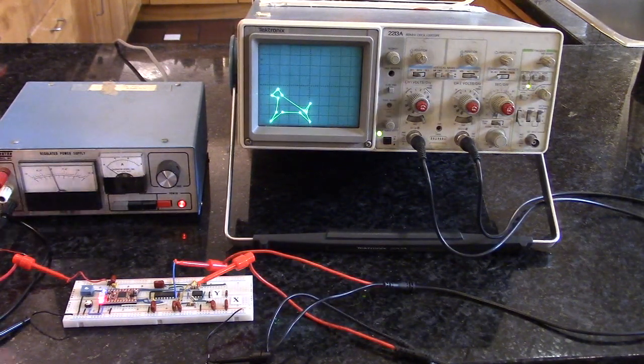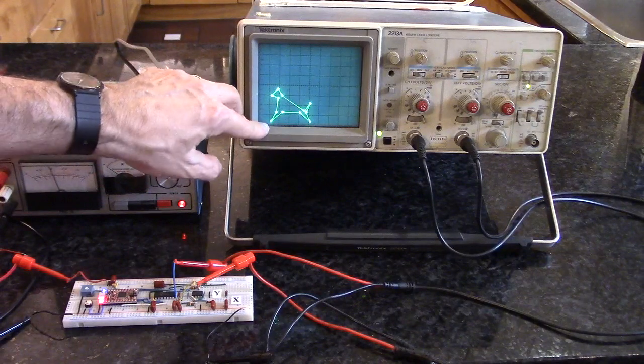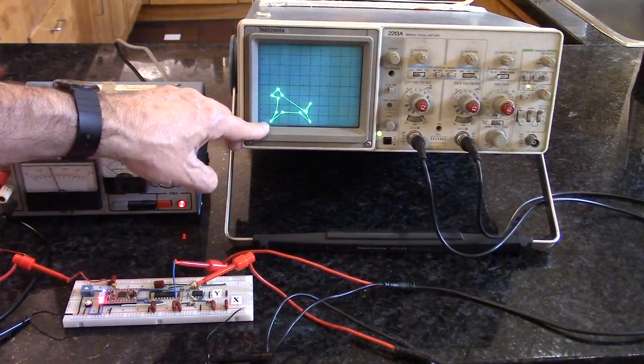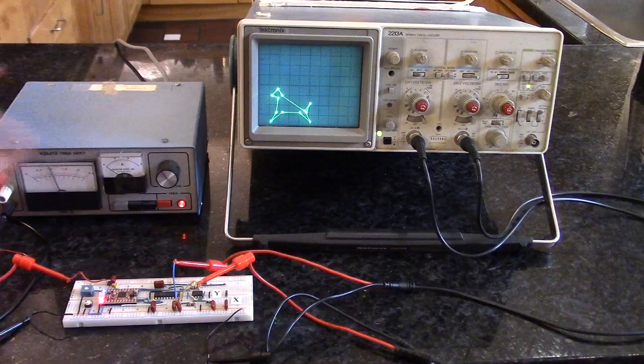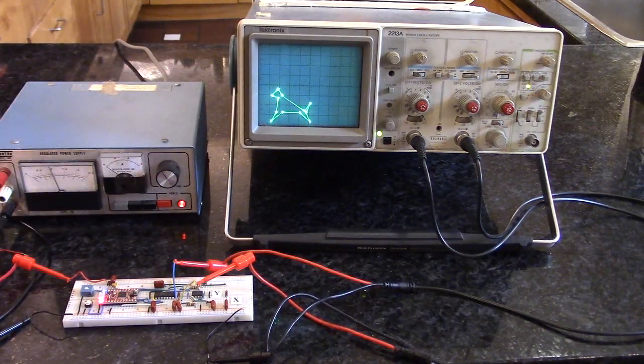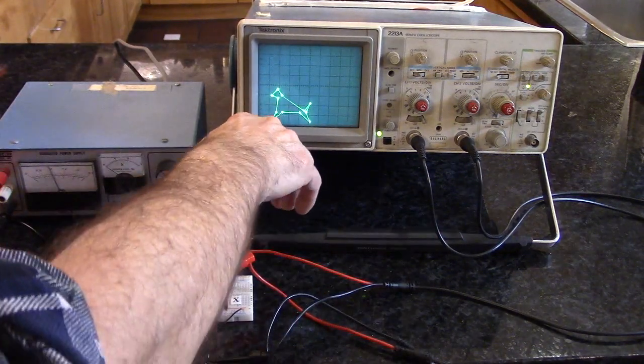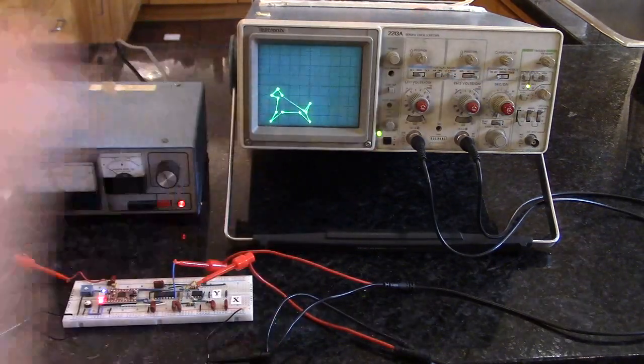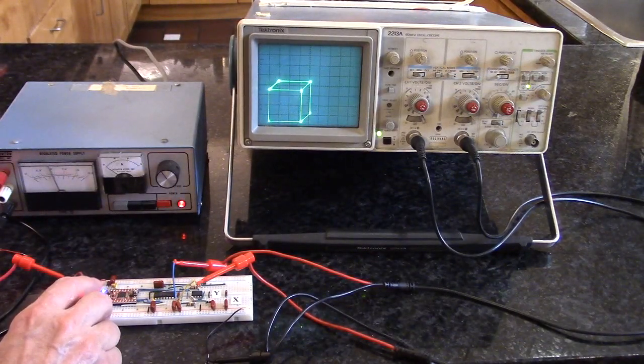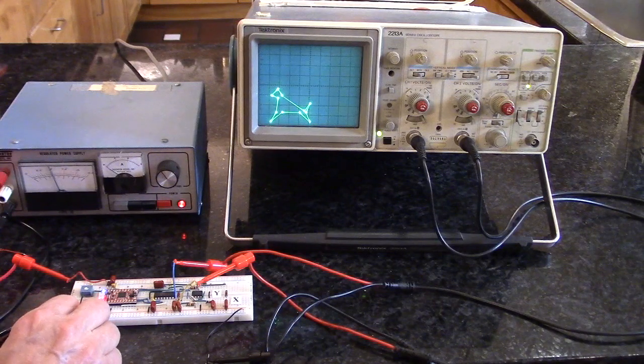256 by 256 is more than adequate. If you wanted to use 4096, you could. I don't think you'd see any difference. Now, you'll notice that because we're starting in the lower left-hand corner, because our output goes from 0 to 2 volts, it always shows something in the left-hand corner. Because the DAC is unipolar, 0 to 2.05 volts or so, we always start in the lower left 0, 0 corner and go to the right. Since these are all approximately the same size, it doesn't make much difference.